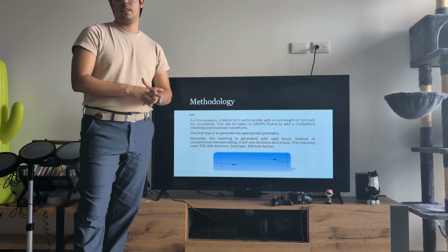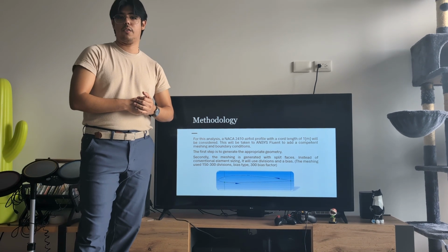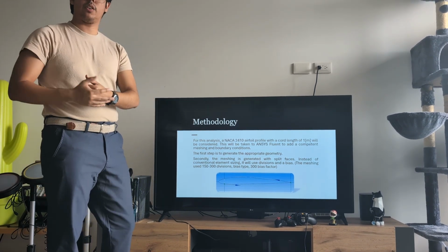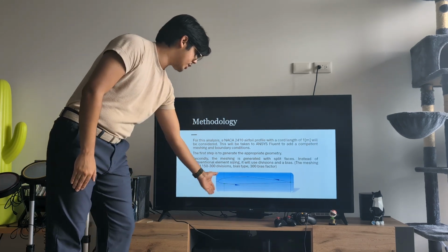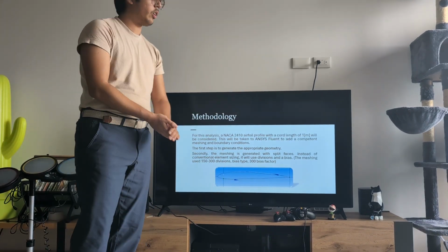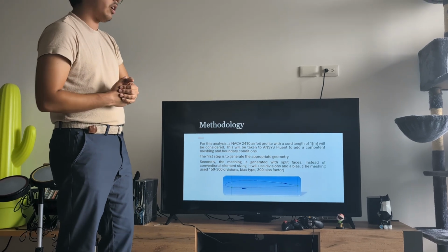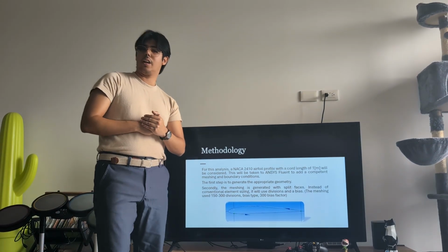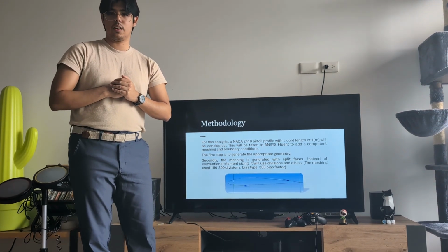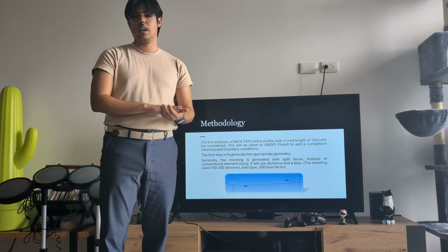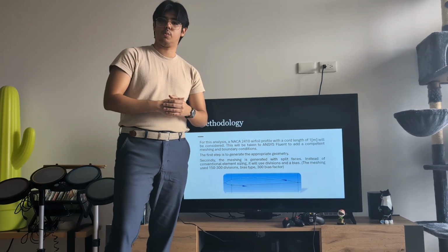And then I draw the domain for the airfoil. This is 15 times the chord length, so 15 meters. As you can see, right here I drew two additional lines, one at the trailing edge, and one 80 millimeters offset from the leading edge. These two will help us to divide into 6 individual faces that have their individual meshing, and this will provide better and more accurate results.